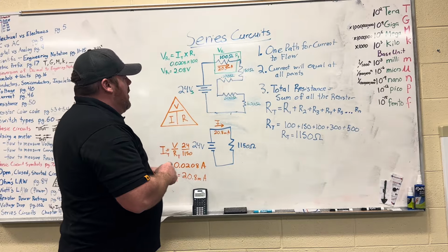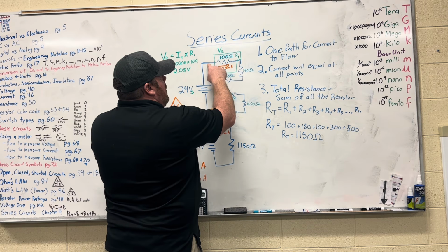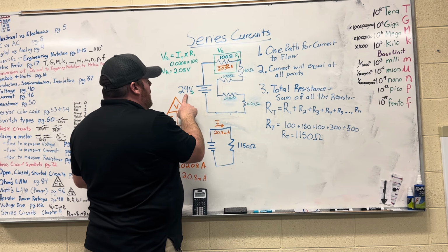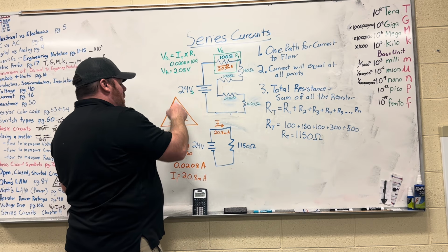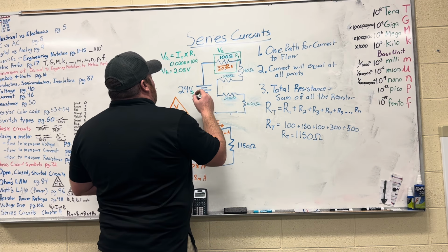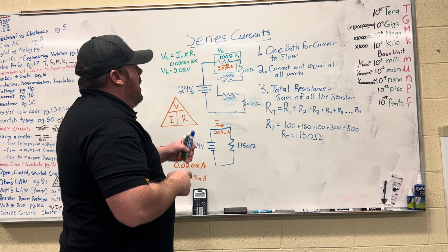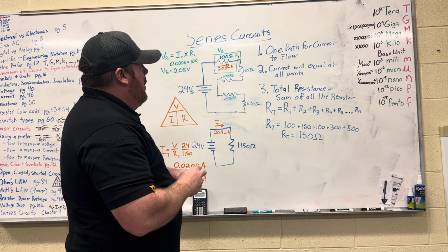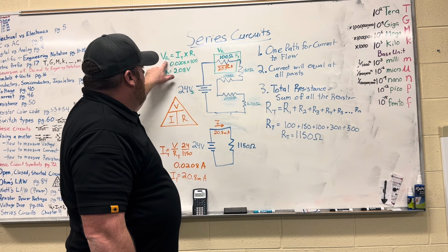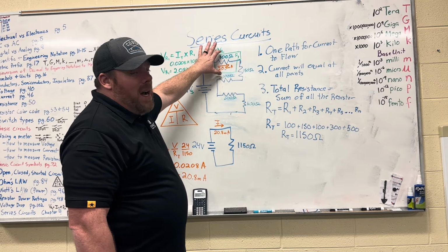That means now if I were to measure with my meter from the reference point here to after this resistor, it would no longer read 24 volts, but it would read 24 minus 2.08, or somewhere in the ballpark of about 22 volts. Now if we continue and do that for all of the resistors, so this was for R1, there's your voltage drop. So the voltage drop across resistor 1 is the total current times the resistor value.